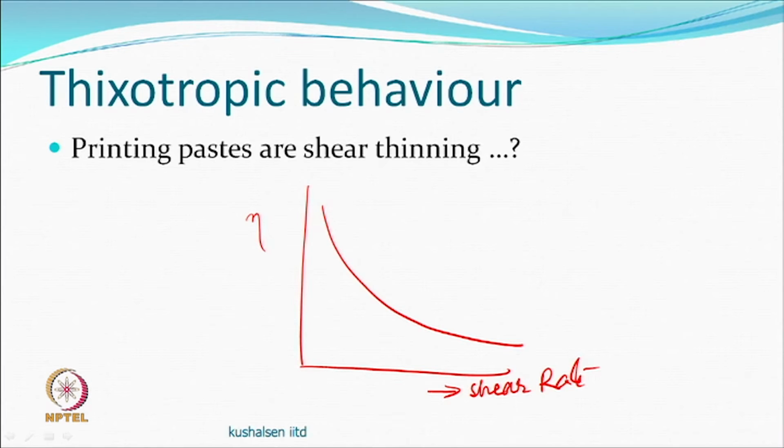But the most important part, even after this, is that when the squeegee is lifted, the viscosity goes back. So, this is the thixotropic behavior in a way. It is time dependent. It does not happen instantly, it is not zero time, there is a hysteresis, but it does reach up, and this is also important for us.